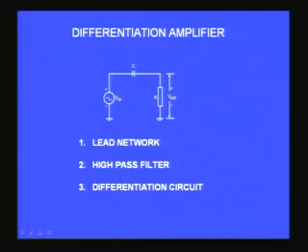To understand that, you can recall some of the earlier circuits that we have already seen. One of them is just a simple network with one capacitor and a resistor in series connected to a signal source V_in. This we called by different names earlier. For example, this was called a lead network when we discussed the frequency response of RC coupled amplifiers. You might recall we discussed in detail the behavior of this simple network which involves one capacitor and one resistor in series, and you take the output across the resistor.